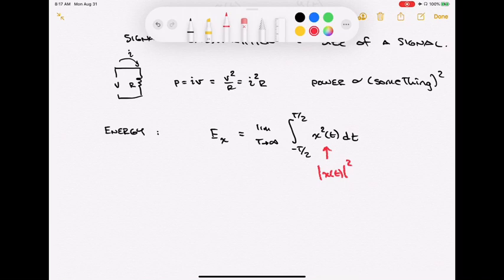The other definition is fine if the signal is real, but it would not handle a complex signal appropriately. So I would just encourage you to go ahead and make that substitution. You'll not notice it most of the time because most of the time we're dealing with real signals, but let's go ahead and do it the right way and do it as the magnitude of a signal squared integrated over all time. So energy is really what? You square the signal and then you just integrate, add up, if you will, all that squared content.